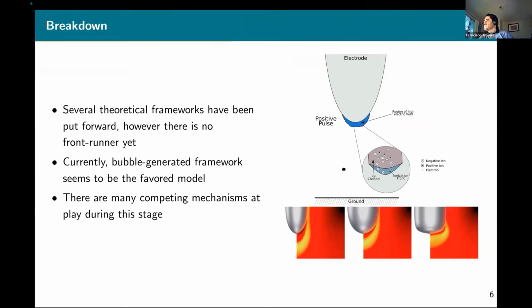We can see the results of this very simple model for 3 different electrodes. You may think, according to these results, that a pointy electrode is favored over the others, but we have the problem that these pointy or sharp electrodes will erode much faster.